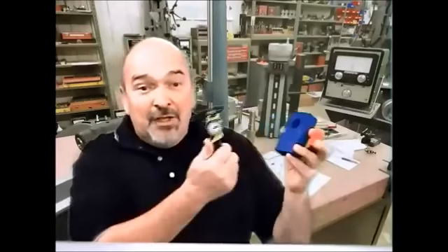use. When inspecting a part, there are lots of different ways to find the center or size. On this hole, I could use calipers, a coordinate measuring machine, I could use a gauge pin, and the list goes on. Unless the part is perfect in form and orientation, these methods can all give you different answers. The 2009 revision of the standard clears this all up by defining several envelopes which are used to determine centers and size for calculating bonus and datum shift.